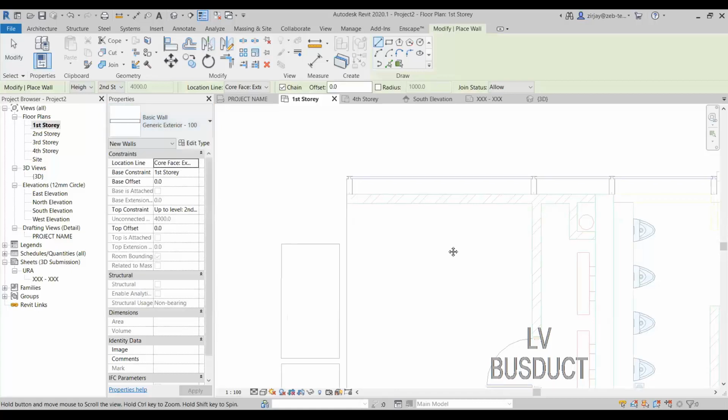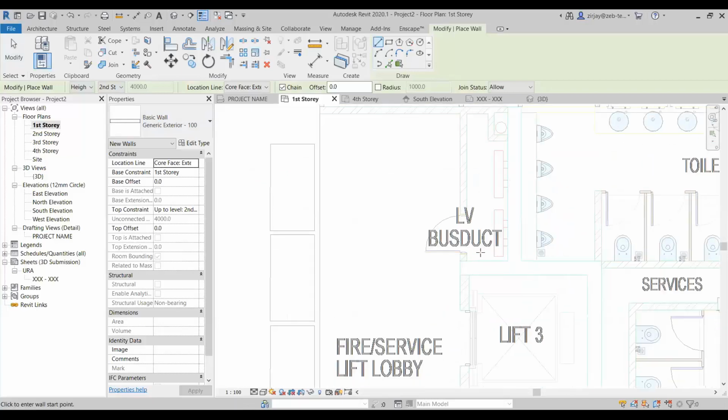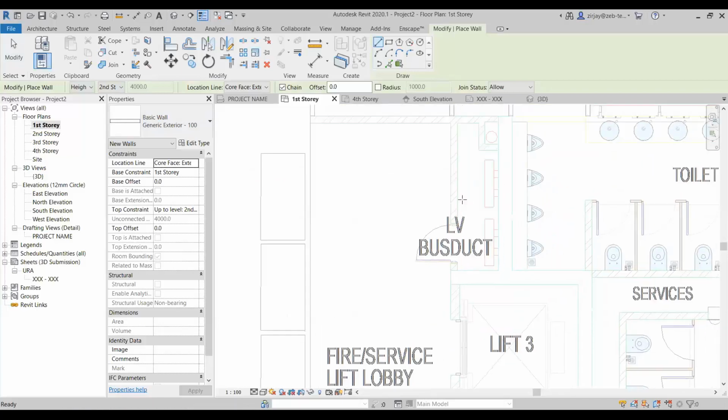Oh, by the way, when we're building in Revit analytical models, we don't care so much about the thicknesses of the walls. As you can see, there's several thicknesses here. The lift core is bigger compared to the masonry walls, of course. But as you have seen in IES, everything becomes like a single plane or a face eventually.